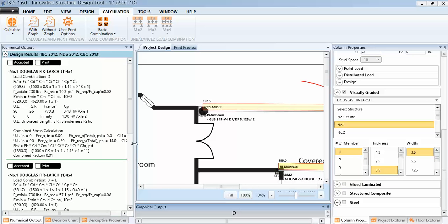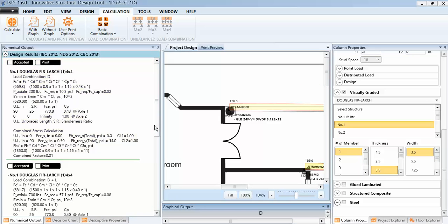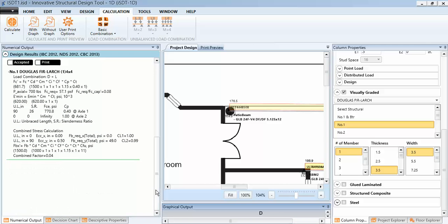So this one is the same idea, it shows all the information, and number one is axial force going on only here, and there's a little bit of side force because of eccentricity, but anyway axial force probably is what controls most here, so number one is 4 by 4, dead or live is adequate.